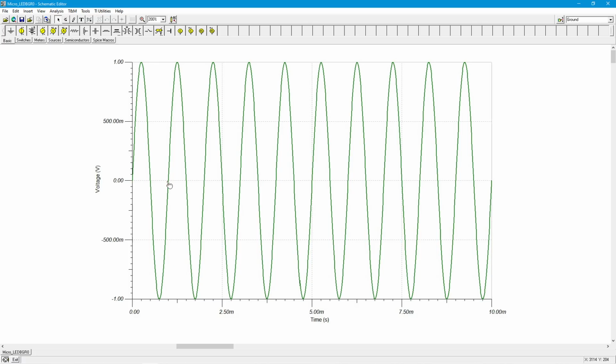But here, I don't really know necessarily when that ADC is going to be called. Now, even if you set up an interrupt service routine to do that, and you actually know at a regular interval, that doesn't help you, as you'll see in just a sec. So let's say that every 2 or 3, let's say milliseconds, just to keep the numbers easy, and I can use my scale here, the ADC call is performed. So you get a value right here. Let's say right at the beginning is your first one. So you get 0. All right, nothing gets lit up.